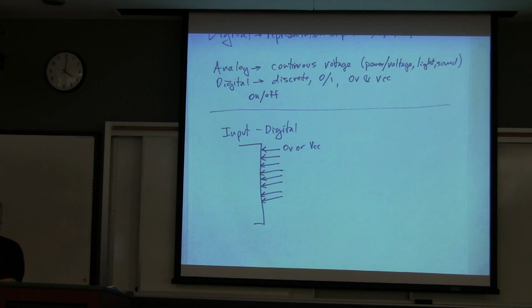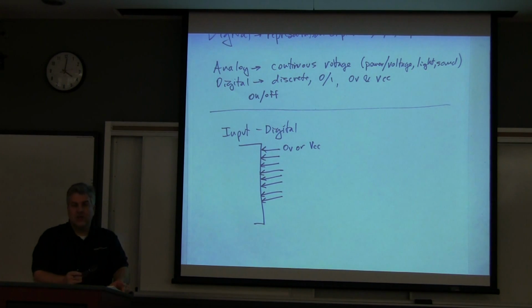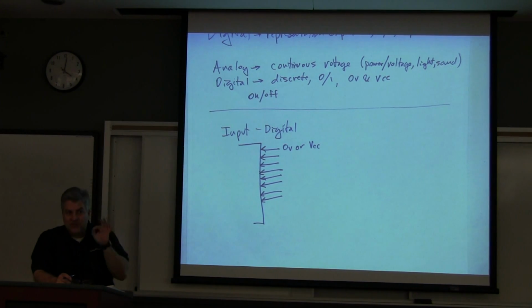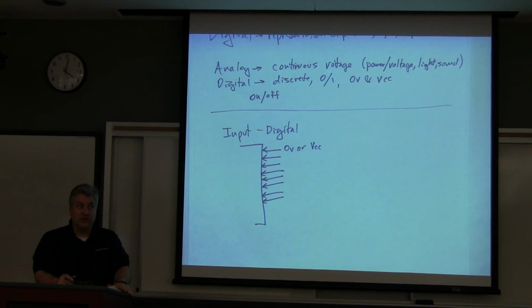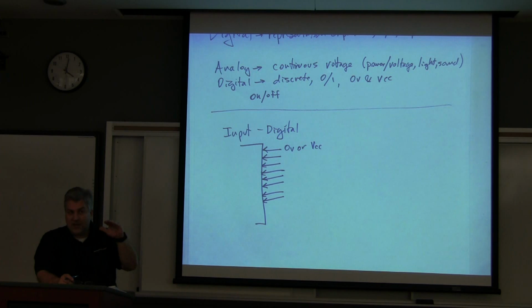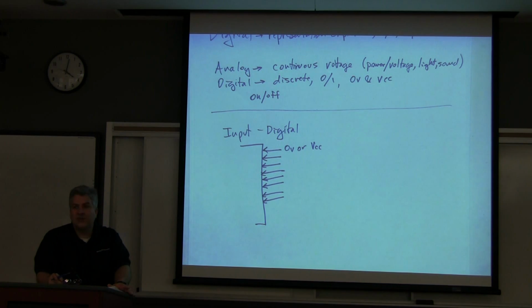Heat. Heat is destructive for a microprocessor, and of course, if you generate heat, which is generated from resistance in the chip itself, you have to find some way to get it out. If you're packing more and more transistors in a chip, you have more and more transistors turning on and off, generating heat. So you can keep the same heat in a transistor that's running at 0.9 volts as in one that has half as many transistors running at 1.8. Actually, it won't be exactly the same. It'll be something different. But yeah, less voltage, less heat. You can pack more and more stuff on it. And again, the worst thing you want to do with silicon is boil it. And you'll boil it by making it too hot.